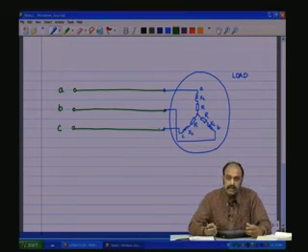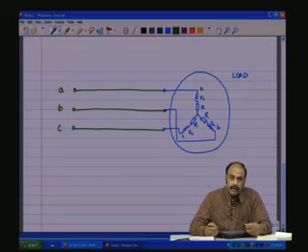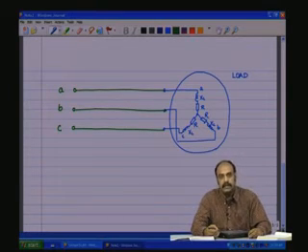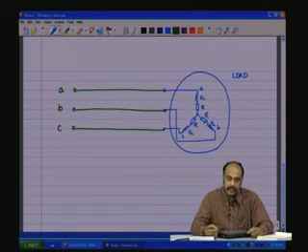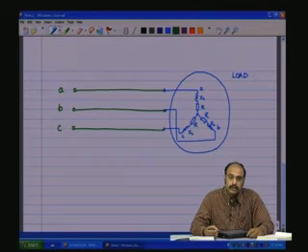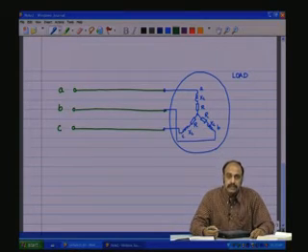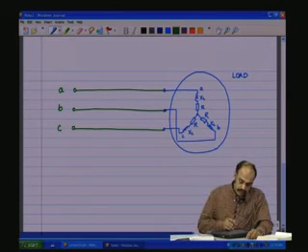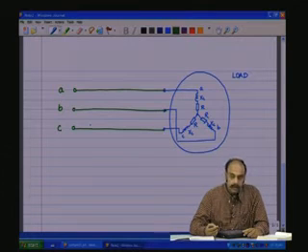Now, if this has a large reactive component, then the power factor is going to be very poor, isn't it? The power factor angle is given by tan inverse of XL by R for every phase, and therefore, if the inductive reactance is very large, then the angle can be large and the reactive power drawn from the source can be quite high.